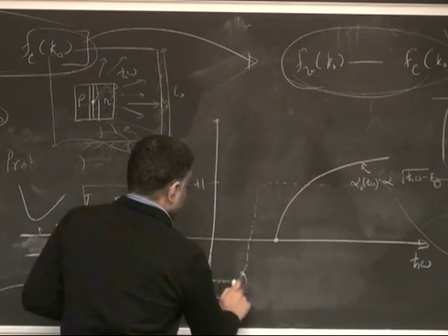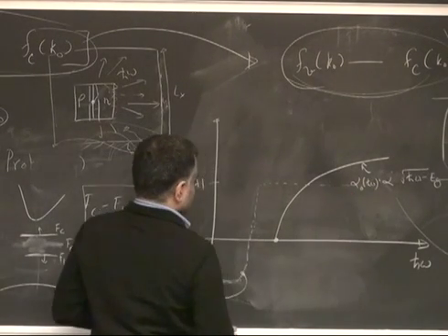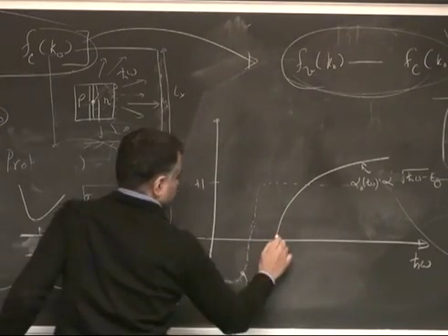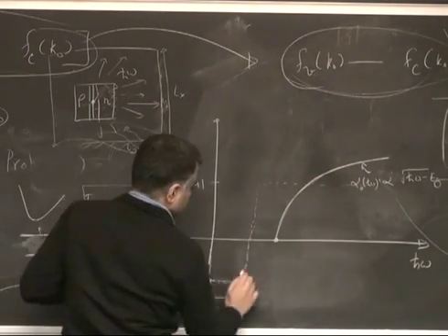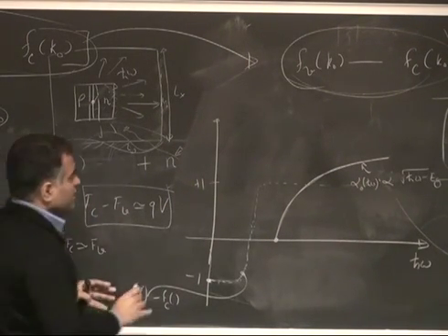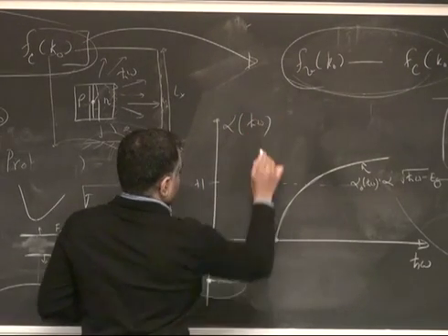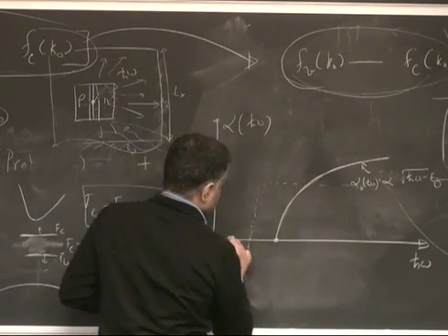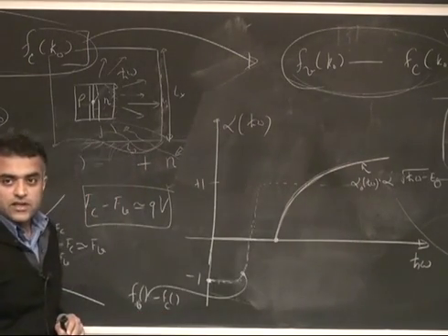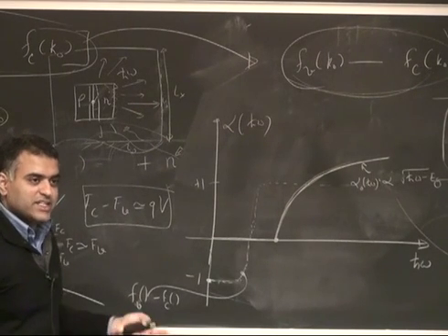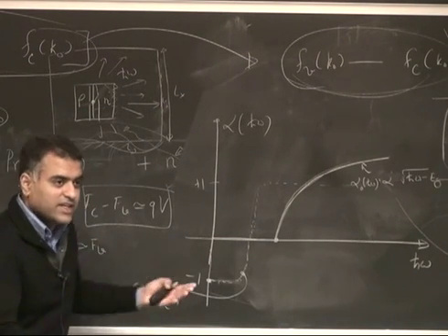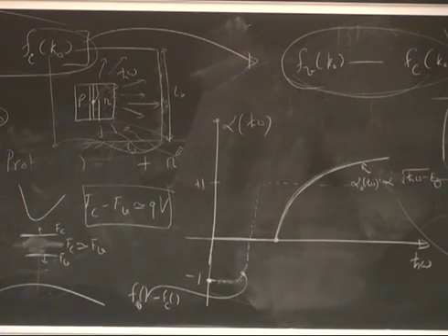And in this situation, the total absorption coefficient is a product of alpha naught, which is this curve, and this whole quantity, which is this dashed line. It's the product of the two, right? Therefore, the total absorption coefficient under this situation looks basically 0, 0, 0, and then it looks just like that. It's not very different. And it has already started emitting light because np is larger than ni squared already. This is kind of already like an LED, but it's very weak right now. The emission is very weak.